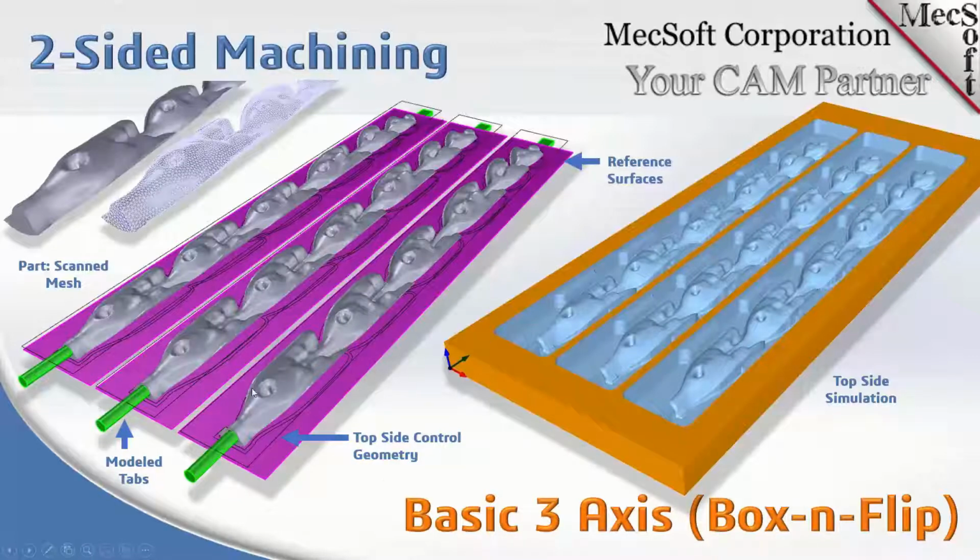The first rectangular curve is to contain the roughing operation. The profile curves in the center of the part are for the finishing operations, and then the purple surfaces you see here are positioned so that the tool, when you do the 3-axis operation, has a surface to land on. In other words, if there's no surface under the tool in 3-axis, the tool will automatically retract to the clearance plane.